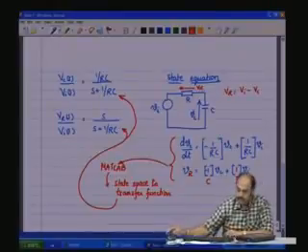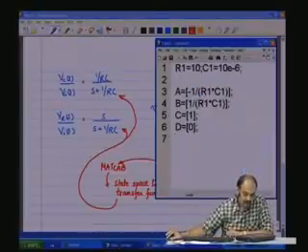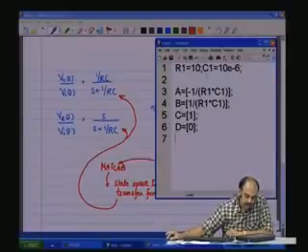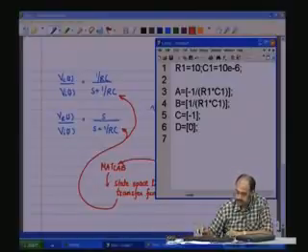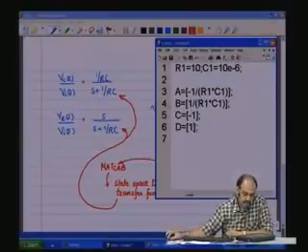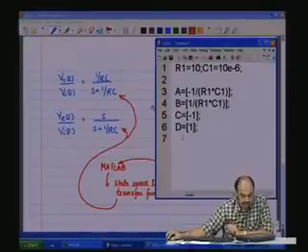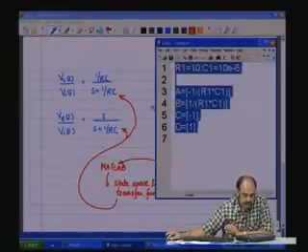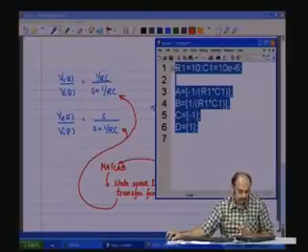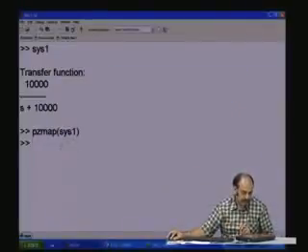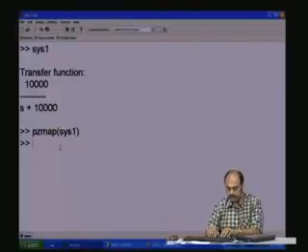This is the change that you have to do to obtain Vr. So, let us do that modification in the MATLAB editor. So, we make C as minus 1 and D as plus 1. So, now with this state equation, this represents Vr as the output, which means we can now obtain the transfer function. Let me clear everything.